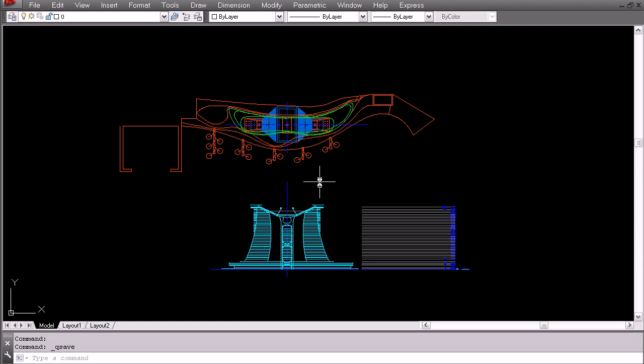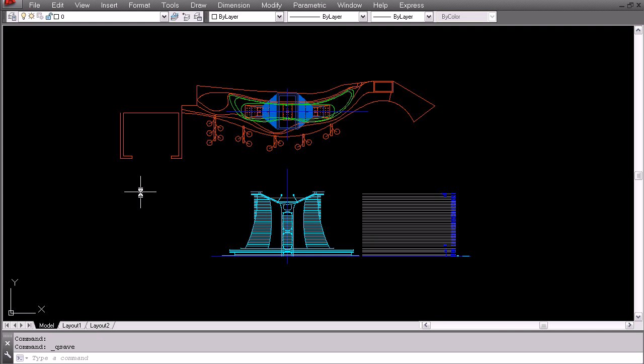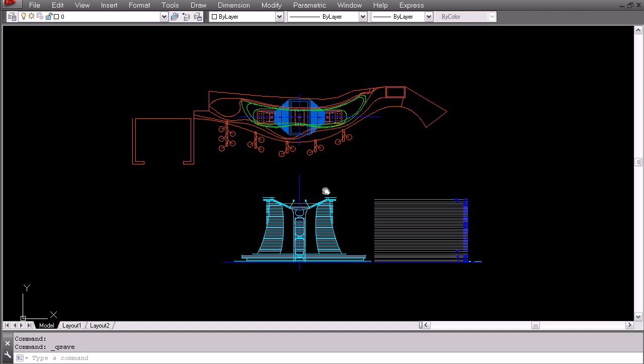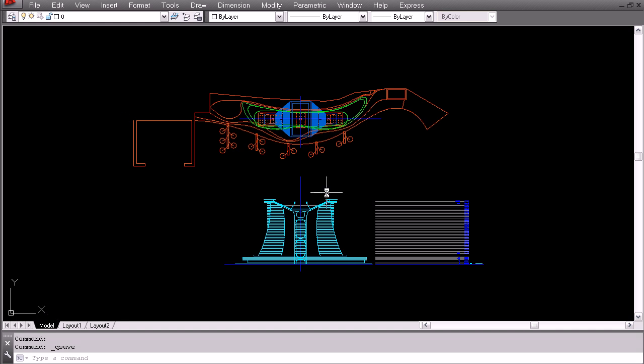Now, an architect would generally give you very complex plans that have tons of information, lots of drawings, lines, hundreds of layers that wouldn't really be understandable. Now, part of this tutorial would have been to show you how to reduce all of that, but since I can't invent a complex set of drawings for this project, I'm going to show you this as being the final result and just explain to you what are the basic elements and the layering that you can use to help you create the building very quickly in 3ds Max later.